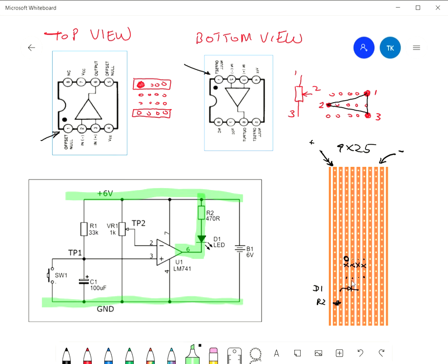So this pin, the copper strip, goes along here. So I'll use this hole here. Okay. So I leave another blank row here just to make space. And I'll use this here to pin 7. This is pin 7, and I'm going to connect this to the positive rail. So what I'll do is I will just put a wire, one end in here, and let's try that again. So a wire to pin 7, which is there.